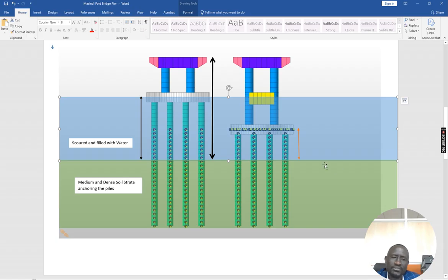So now, 50 years or 34 years or 40 years, you find your pile cap up here, water fluctuates within there, but there's already additional depth of water. That means the water flowing moves here, and then this time this pier scenario with pile cap at the riverbed now has already also some scour depth, which now gives also an extra depth up here.